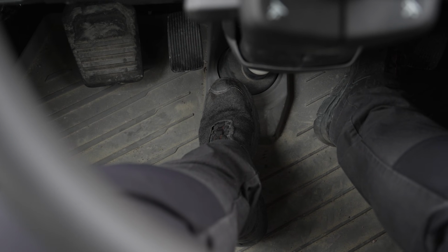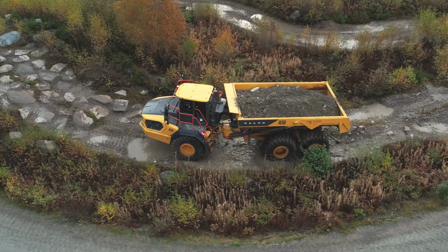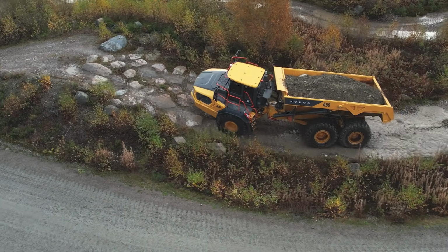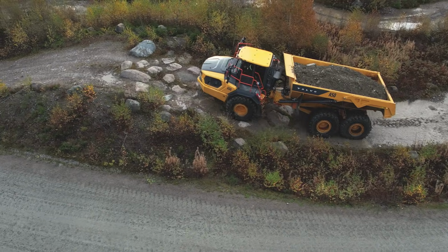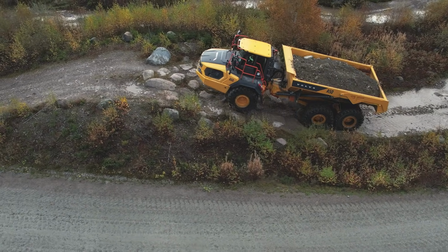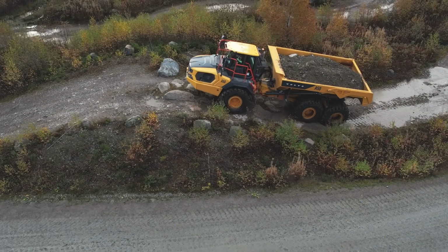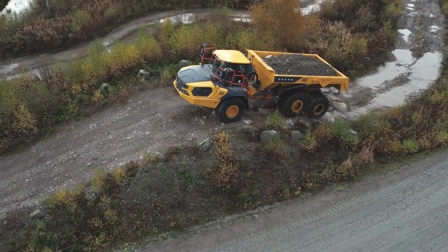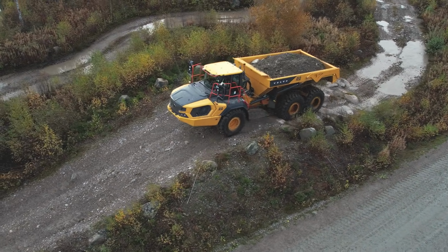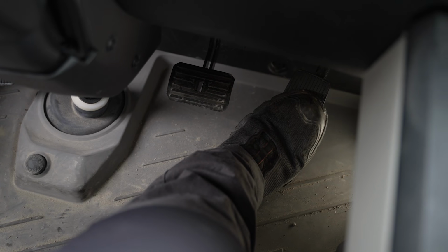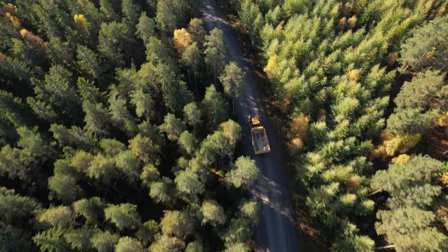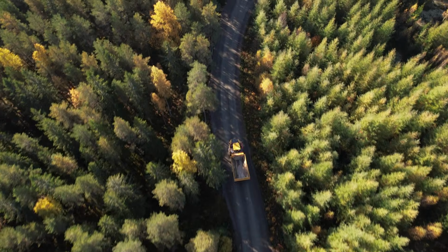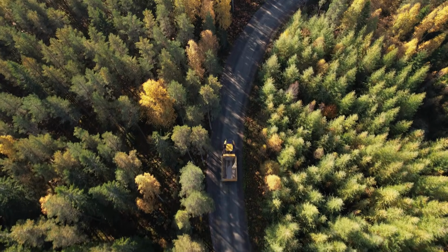In extremely soft or slippery conditions, use the all-diff locks floor button. This will engage all differential locks so that all wheels turn at the same speed as long as the button is pressed. Differential locks may be engaged on the run, but make sure that none of the wheels are spinning. This can damage the differential locks. Release the throttle before engaging the locks, and remember to disengage the locks before operating on firm ground or at high speeds.